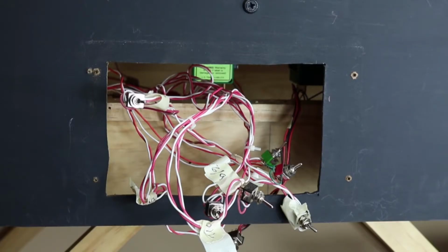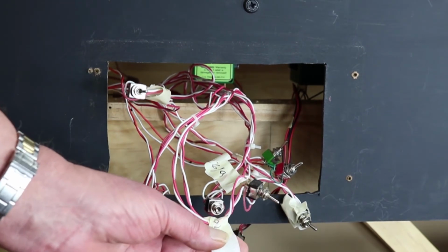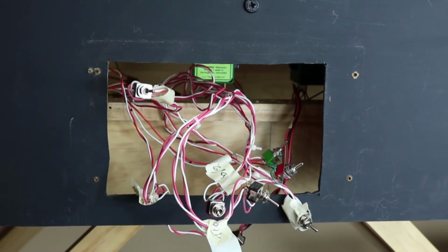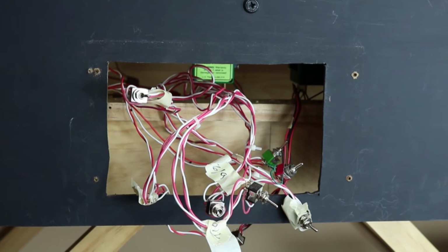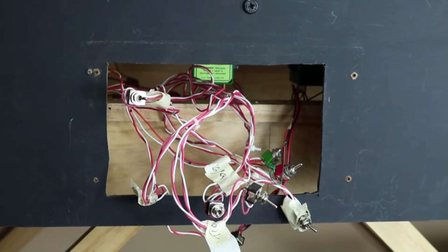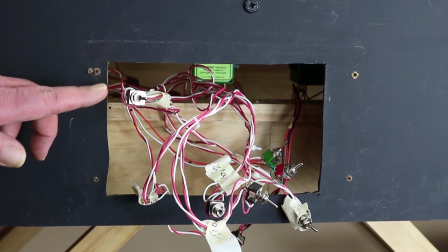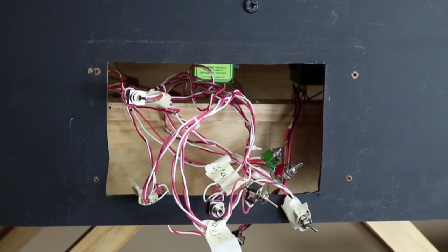To begin our installation, we have removed the old control panel and have labeled each of the toggle switches with the turnout or turnouts that it controls. Now, one thing you should do, and I'm doing that now, is turn the power on. And we just turned the power on. The reason is the contacts on the back of these double pole, double throw toggle switches are really close together. And if in the process of installing one you create a short, you'll know it right away. That's better than putting them all in and turning the power on and having a short and then trying to figure out where it is.